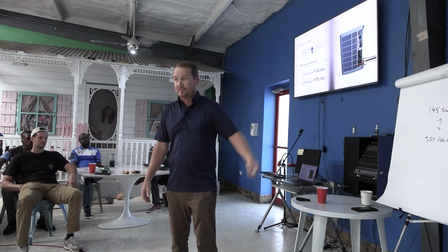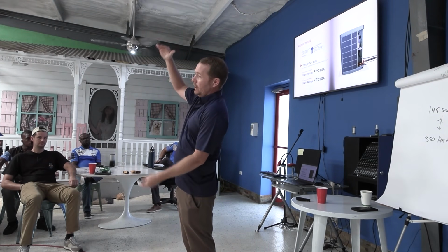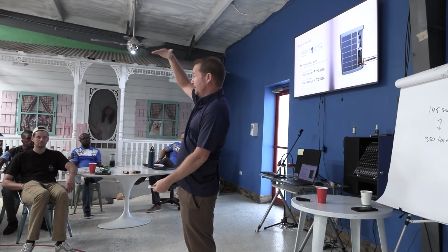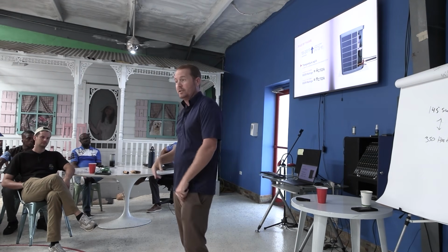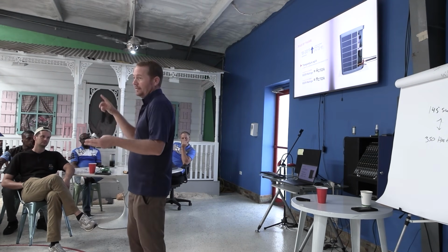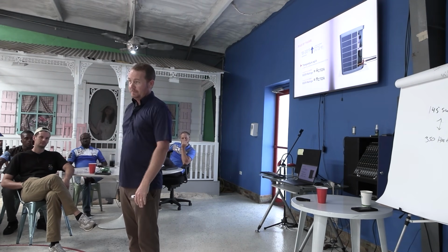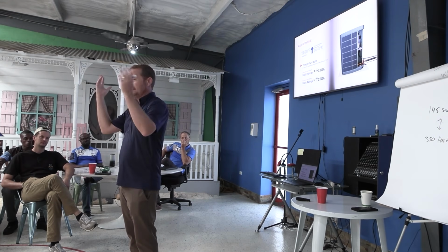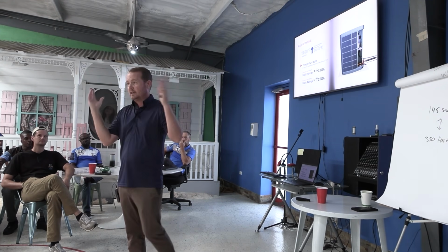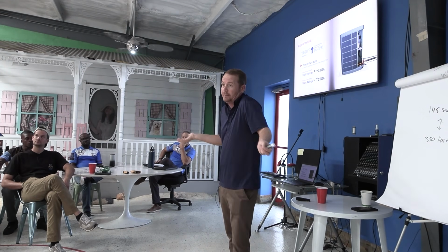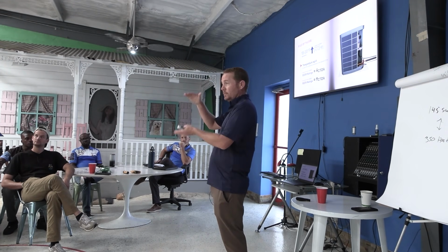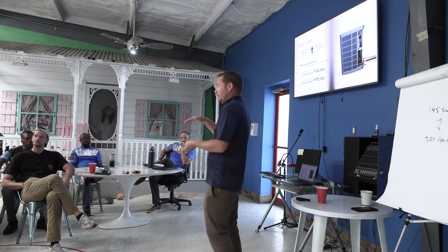Why? Because of this reason. Higher compression ratio, a higher difference between suction and head, because your evaporator temperature still needs to stay the same. Head pressure goes up, that's a higher compression ratio. The compressor runs hot, oil breaks down, nothing works great. Power bills go up, capacity of the system goes down, everything suffers. So we want to keep our head pressure as low as we can, really. There's no reason not to, as long as we're still producing the subcooling that we're looking for.